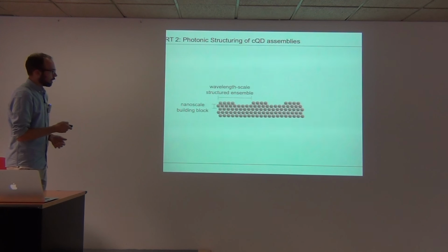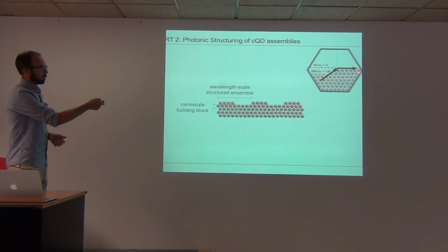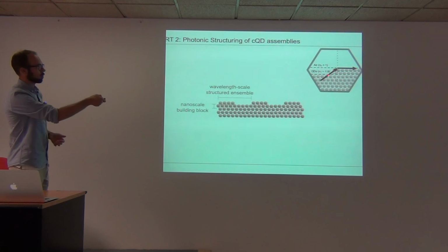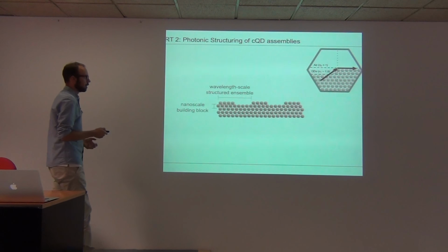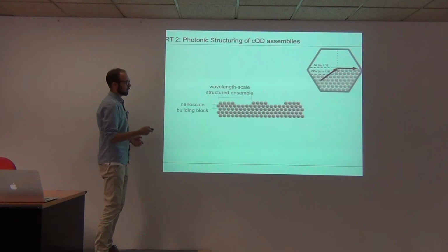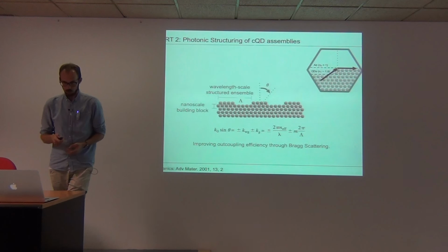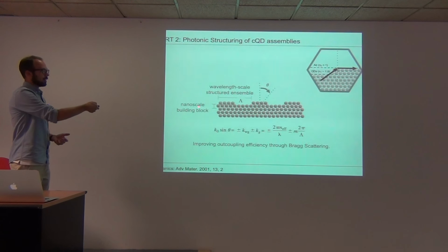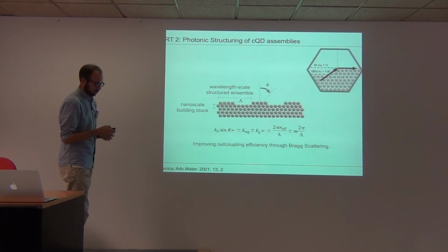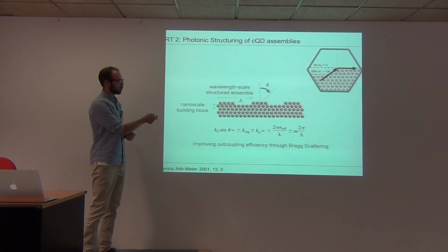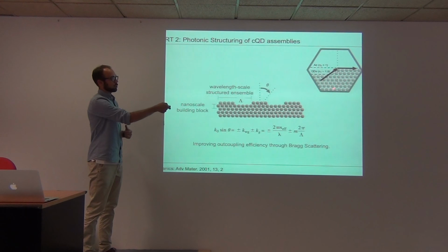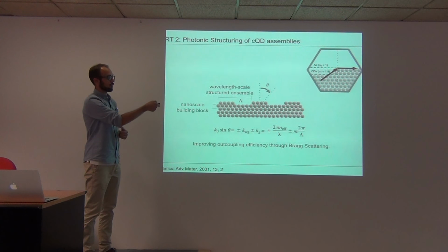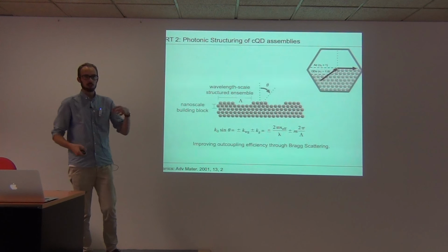Coming back to the original problem of waveguide moding from two slides before, I'm drawing here a grating-type structure, and this is not coincidental, because in organic or solid state light emitting diodes, it is exactly these grating structures that give you Bragg scattering that allows you to couple light out despite the difference in refractive index, because the grating gives you this additional momentum.